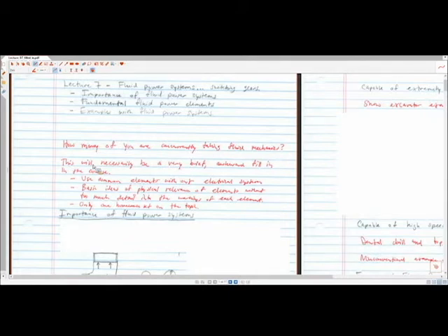We're talking about what's called lumped parameter analysis. So we're going to have certain vessels at a certain pressure, or certain vessels in which fluid is going at a certain flow rate. But we're not going to get down too much into the details of what's happening at every location in the system. We're looking at a broader systems analysis. Your fluid mechanics class is looking at what's happening at each spatial region and trying to understand drag and all those other factors. So it's going to be fundamentally different in the way we analyze this, and it's going to look a lot more like the electromechanical systems we were talking about, not as much like your fluid mechanics class.